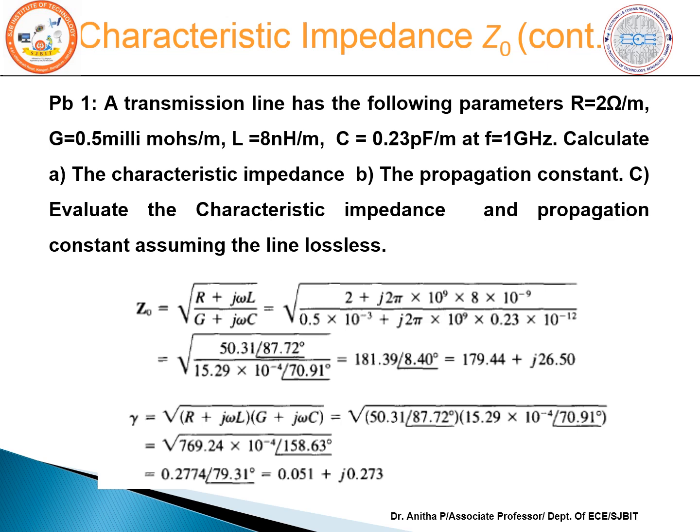Substitute the value of L and substitute the remaining values. As it is given in square root, for magnitudes you can take the ratio and take the square root. And for the angle, when it is a division, as we know, you can subtract the angles: angle a divided by angle b gives angle a minus b. But since it is under a square root, if you take some angle, it will not be a direct square root. You need to take half of that.